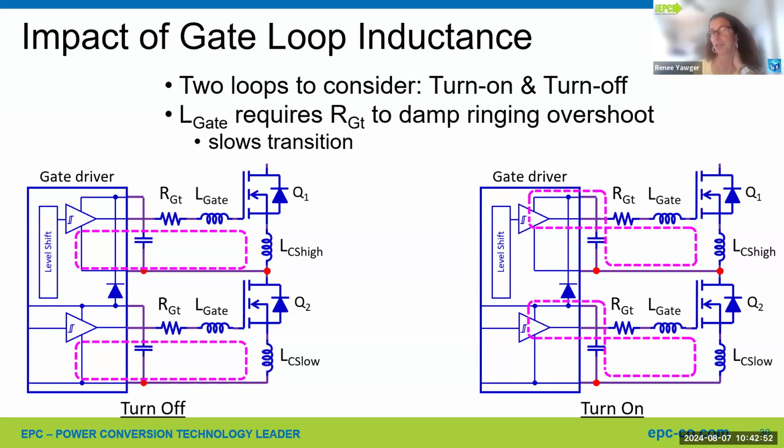Does EPC make high temperature GaN HEMTs for about 175 or 200 degrees C? No, we don't. And that's a good question. I know what you mean. We set 150 volts max. You might say, well, gosh, GaN is a kind of device that can stay as a semiconductor at very high temperatures. And that's true. EPC has done some work at very high temperatures, but the design of the FETs was done to optimize characteristics at 150 volts and 150 degrees C and below. So no, it's not optimized. It's not designed to go over 150 degrees C.